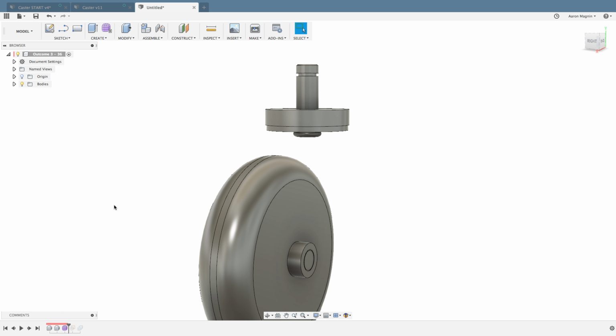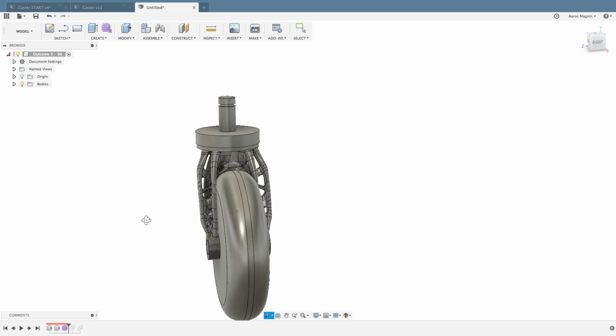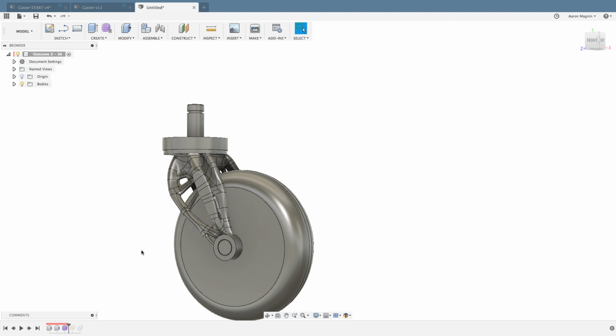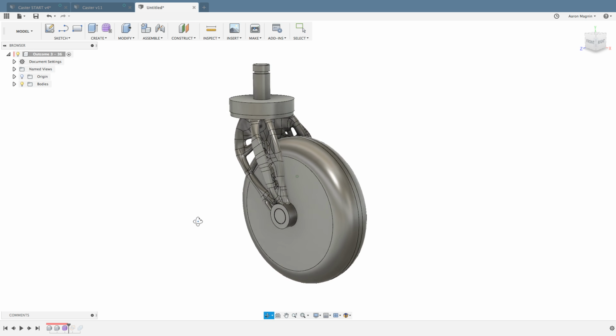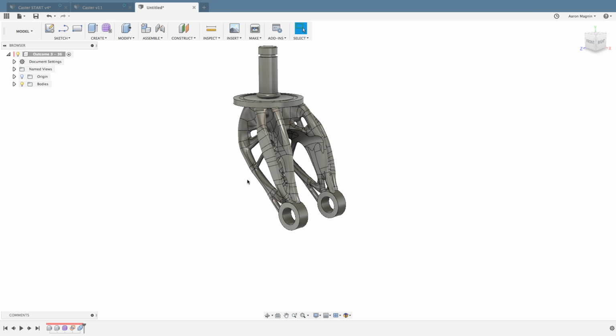From there, the T-spline body does all the craziness between the loading areas and the fixtures, and figures out the way to get there and have the correct strength ratios and everything. That's the next feature that gets added, and then there's a boundary fill that connects all of those, and then essentially there's a combined cut from the obstacles that we had used previously.